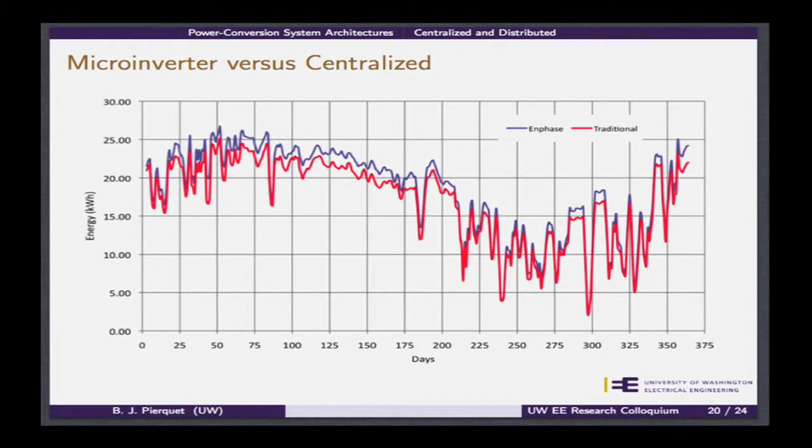And perhaps the centralized inverters might be as well. We were able to capture a significant amount of energy more over the course of a year than a centralized inverter was. I believe it averaged out to something on the order of 10 or 15%. And so that's real numbers. That's real money that you can use to compare the two. And that's ultimately what matters in terms of adopting a new technology: what do I really get for all of this? And so this is at least a quantitative result on the qualitative benefits that we normally get.